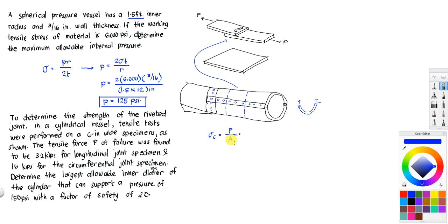So that if, let's say, accidentally I lift 65 kilograms, although it exceeds my maximum allowable, because of the factor of safety, I still won't break. Okay? So in engineering, we need what we call a factor of safety. A margin of error, no? Sometimes in construction, sometimes in manufacturing. So we cannot give the maximum load that it can carry, up to there only, because more than that it will break. So we have the factor of safety. Normally, we divide it by 2.